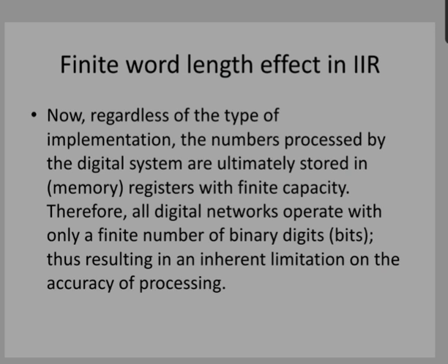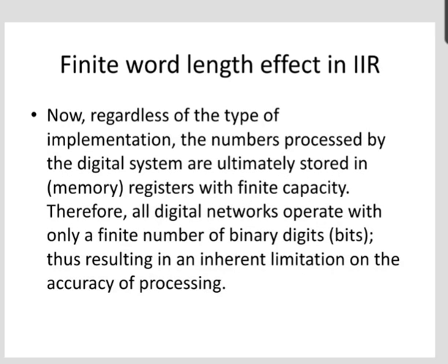We know that the computer stores numbers not with infinite precision but rather in some approximation that can be packed into a fixed number of bits or bytes, because of which we are losing some information. So the effect of losing this information on the response of digital filter, this effect we call finite word length effect. There are a number of finite word length effects like overflow error in addition, round off error in multiplication, effect of coefficient quantization, limit cycle, etc.